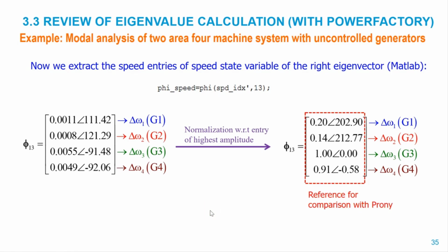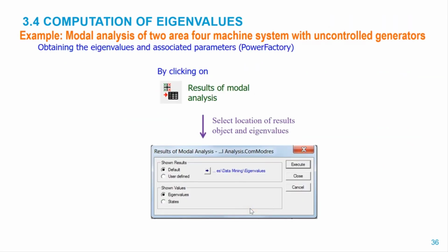We are going to compare again the normalized amplitudes and phase shifts that we will take with Prony for the rotor angle signals, or could also be from output power signals. Then we try to see if we have similar proportions in magnitudes and angles between the different estimated amplitudes from the different signals of the different generators.